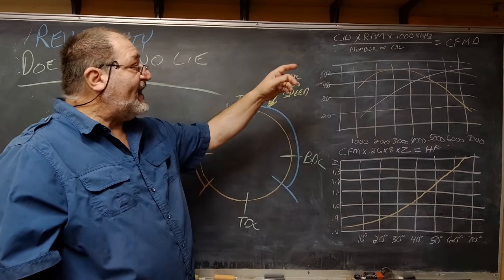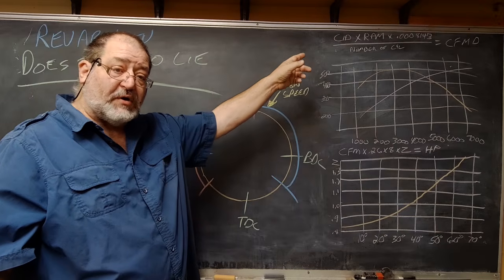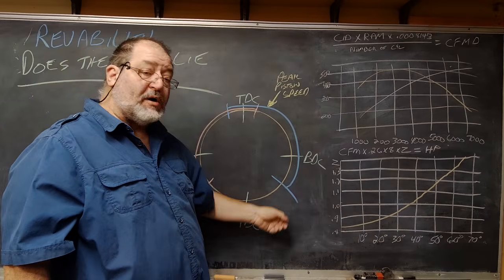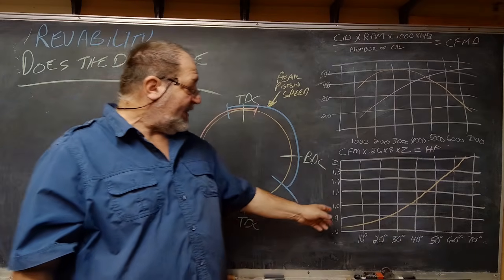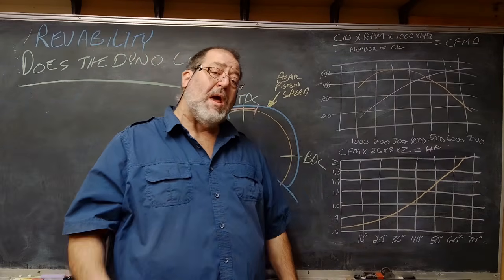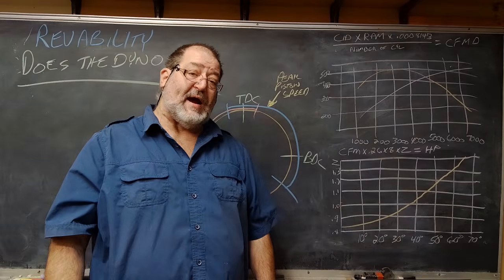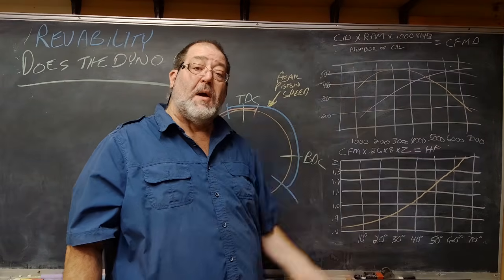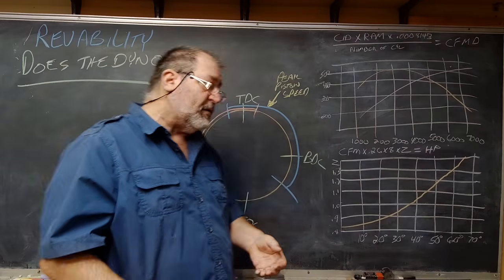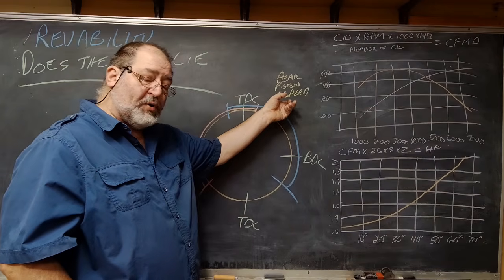You add more cam and it just doesn't work. If you don't have the airspeed right, the cross section correct, this won't work when you get up to really big cams. You stall out at a ZL1 because you don't have the airspeed to carry more. So sizing is important, but then when sizing is important, this fill becomes more important.